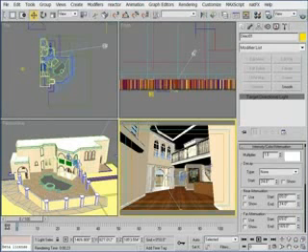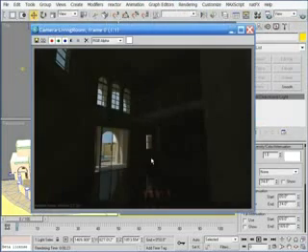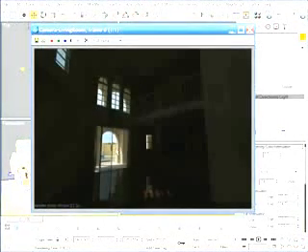But before I can do that, I need to make sure that the outside of my scene is illuminated realistically right now, because the outside is only illuminated by one light, the light representing the sun. And if I don't get it right now, I'm setting myself up for failure because I'll have to adjust the sun intensity multiplier or color mapping eventually, and doing it after I've set up my interior lighting will only mean that the interior lighting will be completely thrown off.